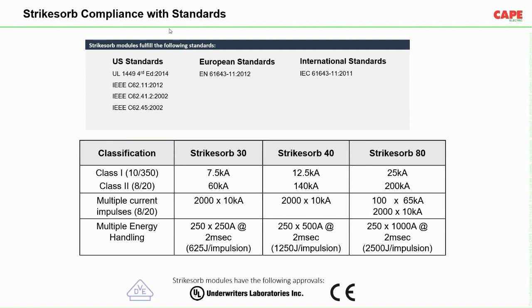At the main panel or elsewhere? You see, we cannot answer immediately in this case. We have to find out how the whole electrical installation is designed, and then what kind of protective measures you already have and what kind of protection is required for your equipment. So the correct answer to your question, where to put SPD in any hospital.